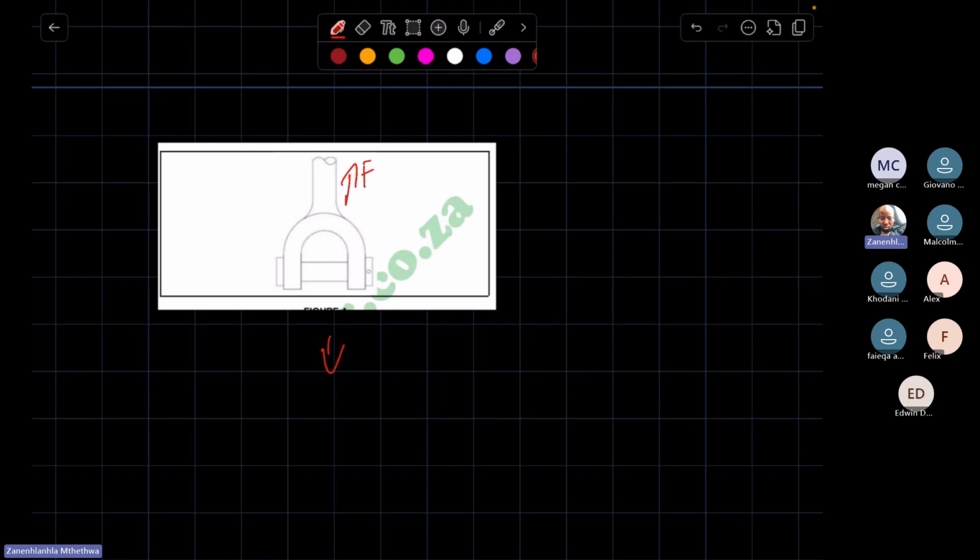Because the problem is based on the pin, we look at the forces that the pin is being subjected to, and those forces would be right here and right there. So you have Fs here, you have Fs there. Essentially, the approach is the same. Do you see that? Those arrows for Fs, they are going up if the pin is pulling down.